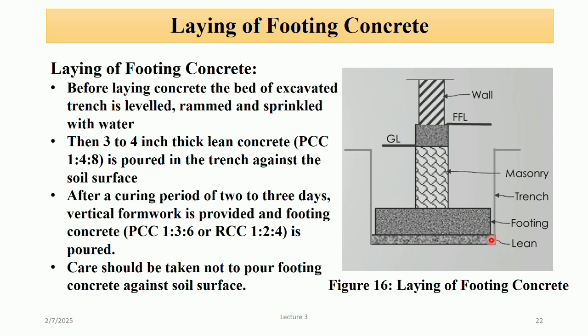Then we start curing of the lean concrete for up to 2 or 3 days. Then we erect formwork, vertical formwork, and we provide our concrete of ratio 1:3:6 or 1:2:4.